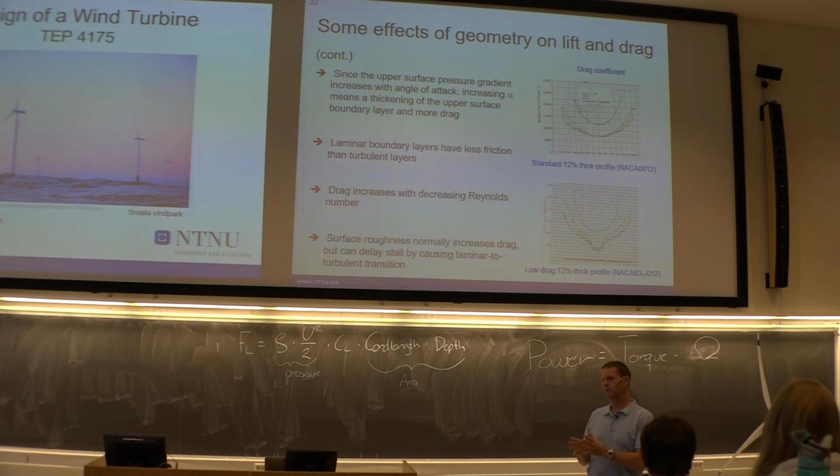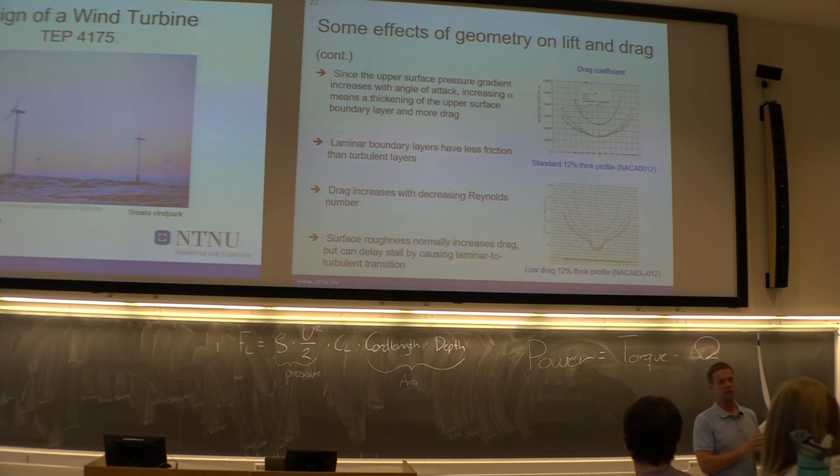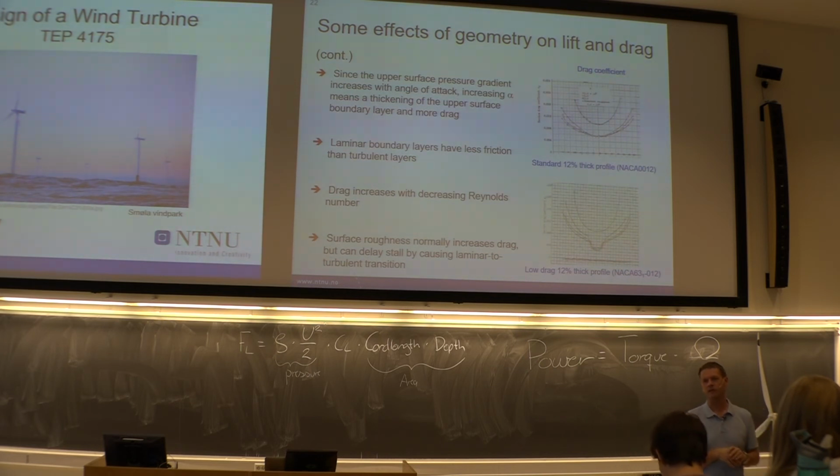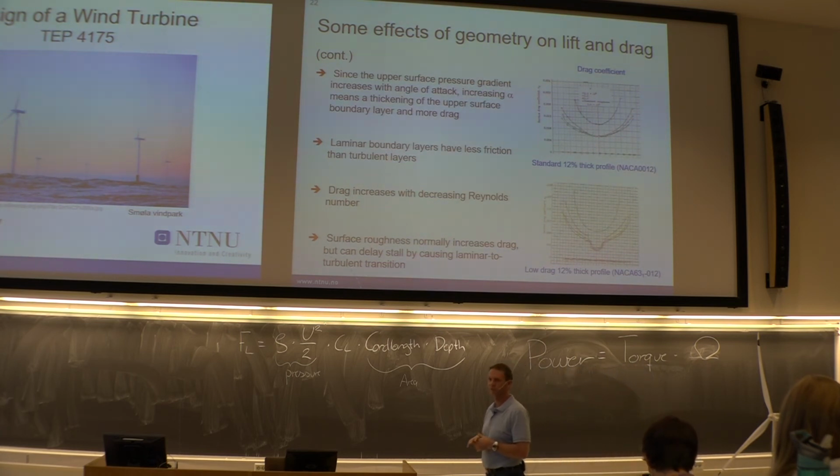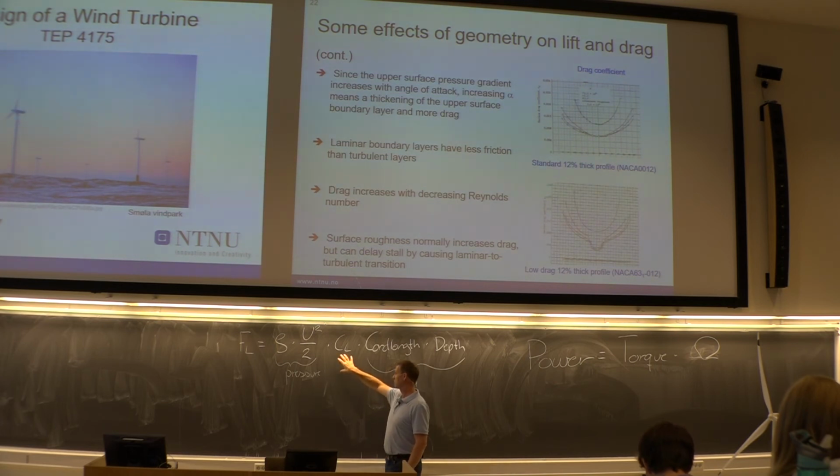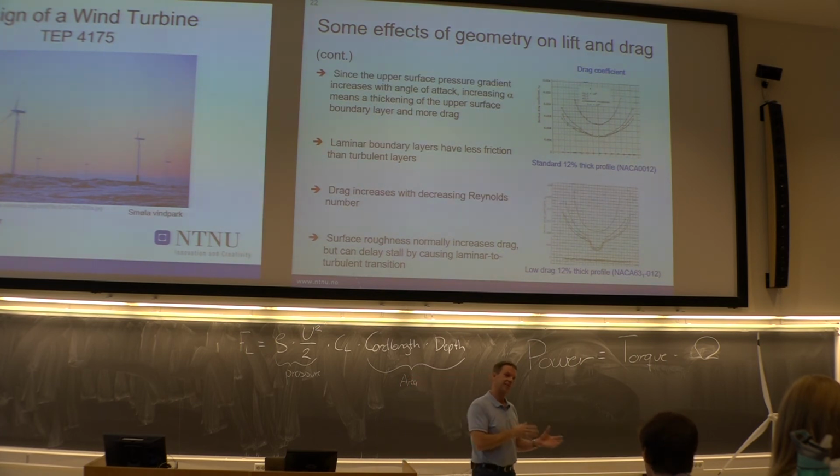We designed it here, and we tested it in the wind tunnel, and we almost never came into turbulent flow for that turbine. It never gave us any of the results we were expecting, because all of the calculations we had done beforehand were based on these coefficients, which were based on turbulent flow. So laminar flow is a different story.